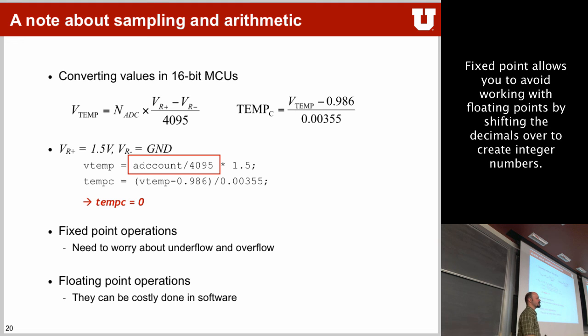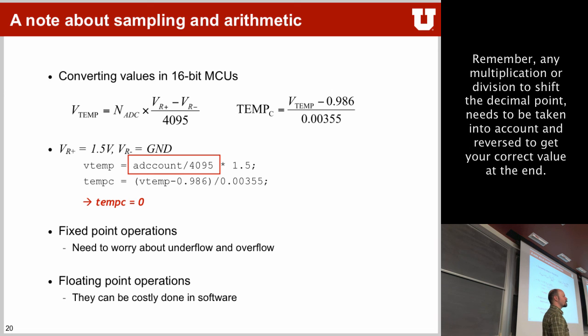So you have to start playing tricks and shifting the decimal point around, right? So for example, in this case, we have multiplication by 1.5. So what you could do is multiply it by 15 first, right? You get a higher number, an integer. Now the problem is, you could divide it now down by this number, and then divide it by 10, you will probably get a very small little integer, potentially.